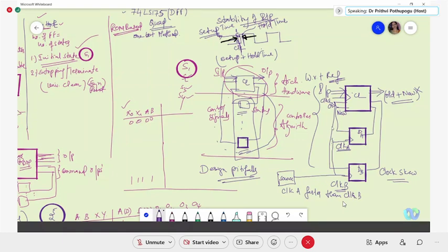So if different wire lengths are used, that itself generates a clock skew, because the source is placed a little bit nearby to B flip-flop, and a little bit far away to A, and a little bit far away to your hardware. That means combinational logic. That means that the clock that is generated will not be synchronously reaching all the elements in the design.